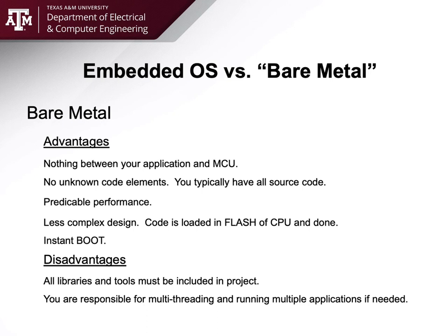That's also the advantage. It also has very predictable performance. It's going to do exactly what it's told. Every clock cycle is very predictable. It's usually a less complex design. I mean, it is the code that you have there: all of the header files and the C files combined in one project. That's it. There's nothing else. You can load it, flash it to the CPU, and you're done. And because of that, it's instant boot. The very first instruction is your application code. So you could do things like instantly set all of the I/O lines correctly and things like that.